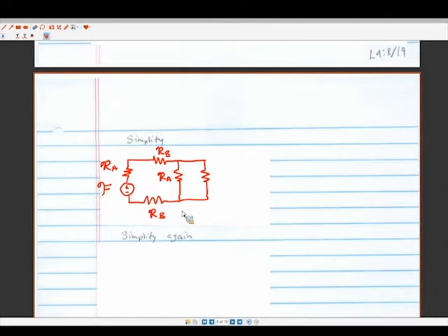So in series, they add, right? Resistances add in series for electrical circuits, so therefore for magnetic circuits, same thing. So we had 2RB plus 1RA. Okay, next we have RA is in parallel with 2RB plus RA.